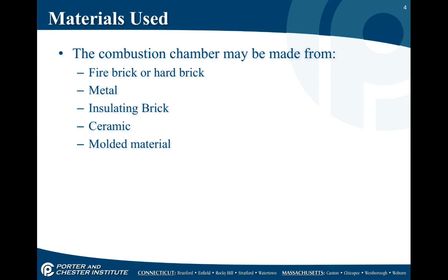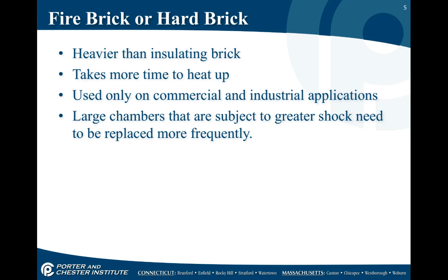Combustion chambers can be made up of fire brick, hard brick, metal, insulating brick, ceramic, or molded material. The fire brick is basically used in large commercial industrial applications. For example, you'd see it used in a power plant or multi-story buildings. It's much heavier than insulating brick. It takes a lot of time to heat up. The nice part about it is it does hold the heat.